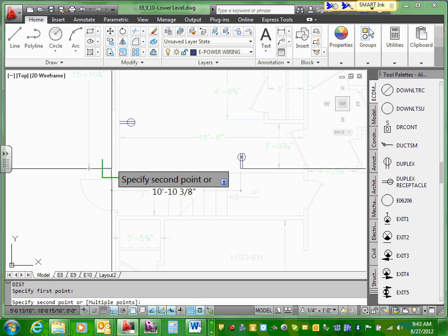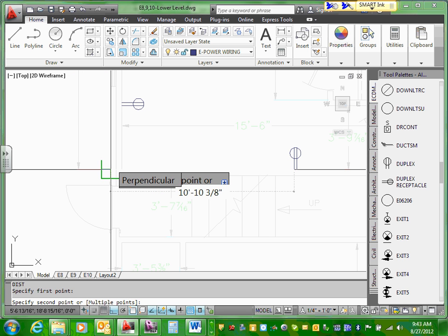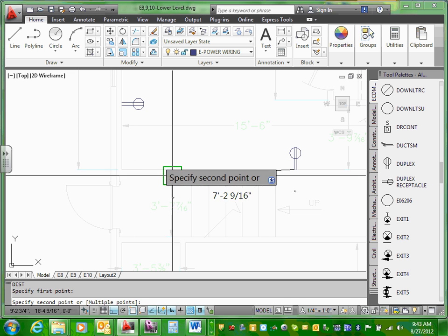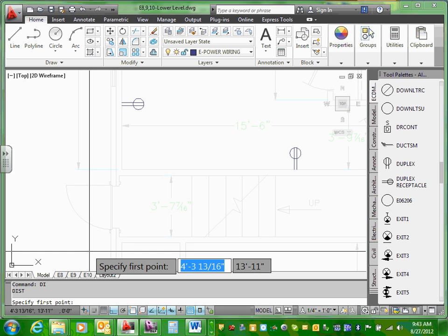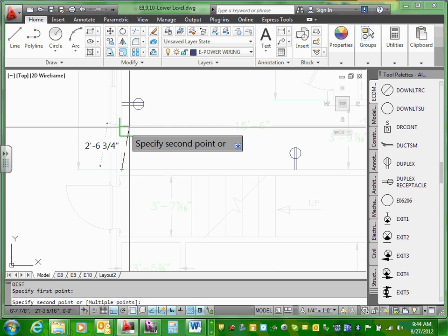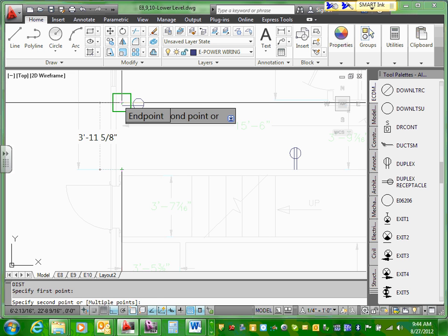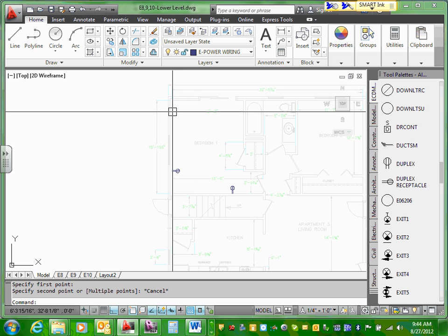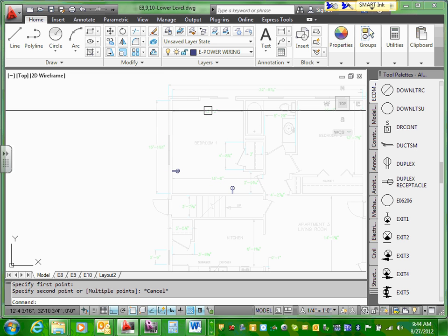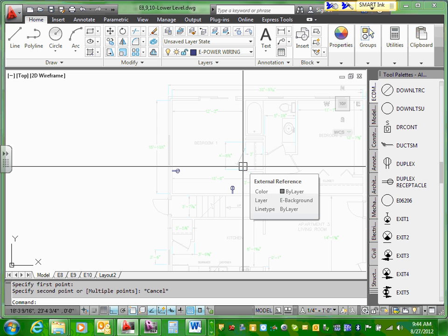Remember the rule, here's 10, right? From here to here is 10, and definitely this is more than 12 then, right? Can you guys see that? So almost 10. If you go DI again, from here, enter, and you come from here to here. See, this is definitely more than 12. So what do you need to do? You need to drag it down, so you can adjust your receptacle. Most likely you end up with one receptacle here, one here, and you measure them. Can I have thumbs up that you know how to first lay them out in the middle and then readjust and make sure 6 from every opening, 12 in between? Cool.